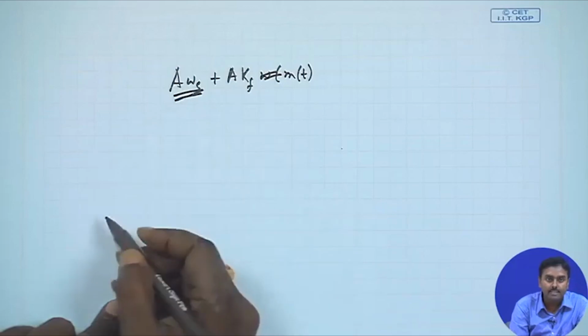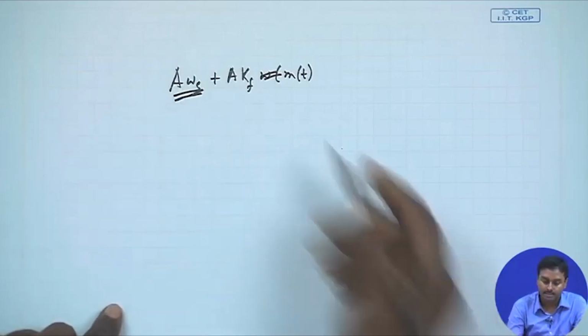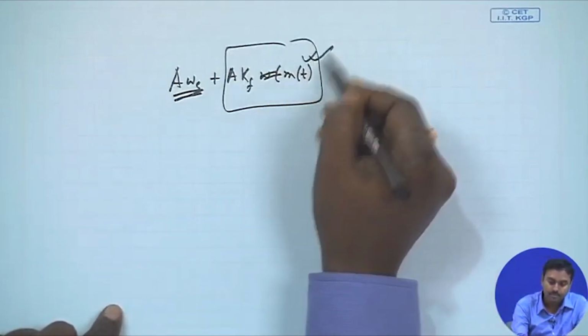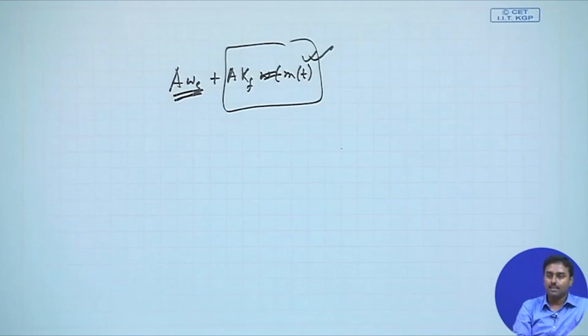Now, this is just a DC term. You block the DC with a capacitor, and you will get this part, which is the message signal. So, this differentiator induced method of FM demodulation is very simple. All you will have to do is find an ideal differentiator circuit. Now, we will discuss that, it is a little bit difficult to find an ideal differentiator.